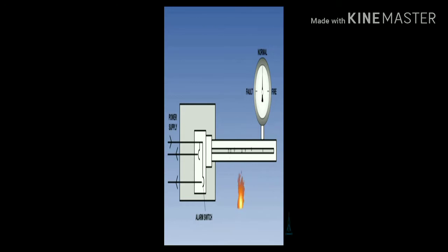The fire detection control unit monitors this resistance. If the resistance decreases to the overheat set point, an overheat indication occurs in the flight deck. Typically, a 10-second time delay is incorporated for the overheat indication. If the resistance decreases more to the fire set point, a fire warning occurs. When the fire or overheat condition is gone, the resistance of the core material increases to the set point and the flight deck indications go away.